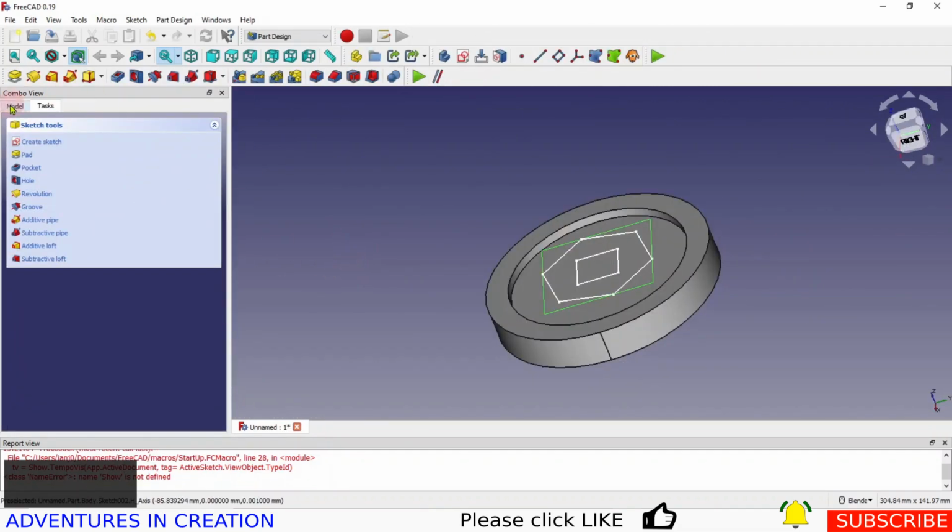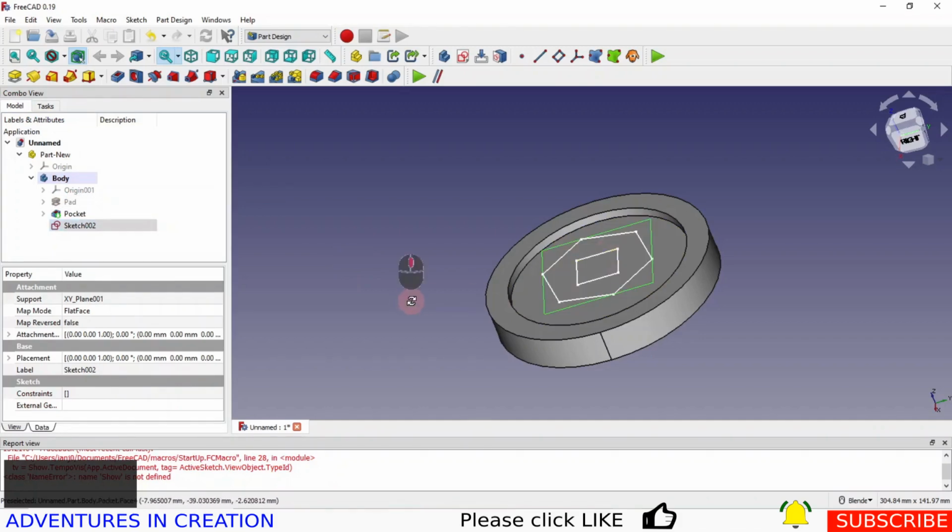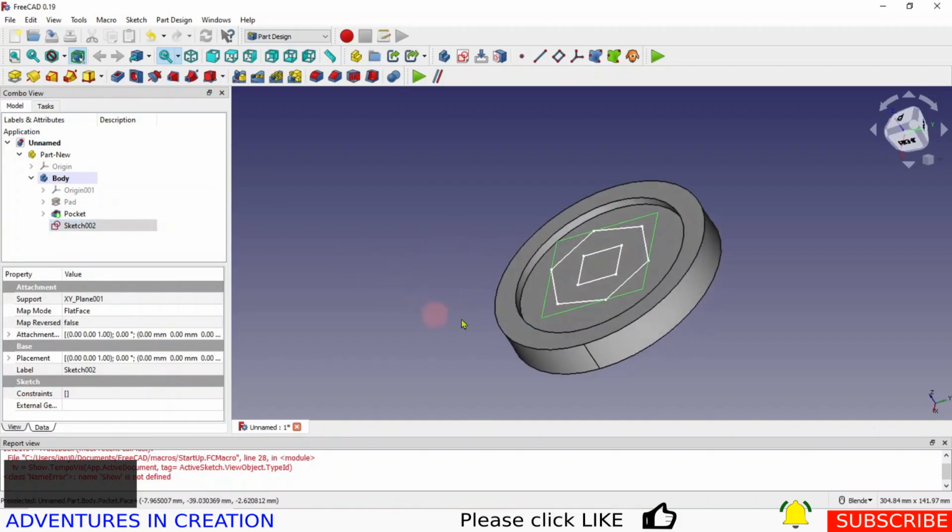So now I have a sketch that is sitting on that XY plane. It's actually above, it's level with this surface, not this surface, because it's on the XY plane. I could offset it if I wanted to, but I'm not going to, because we can tell it the depths when we come to do our pathing.